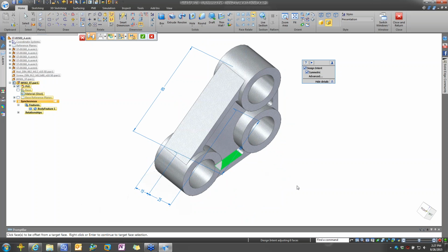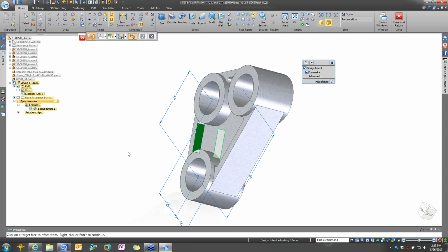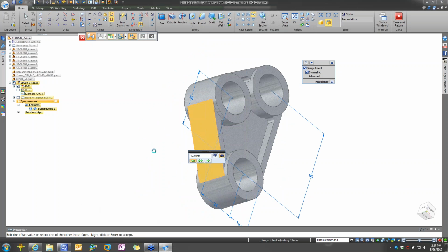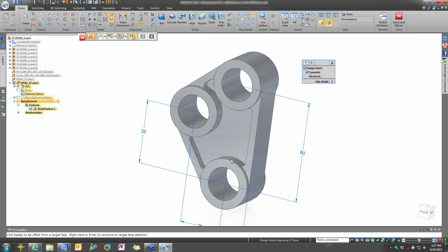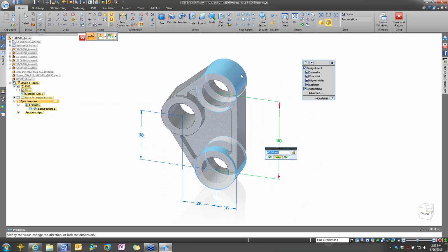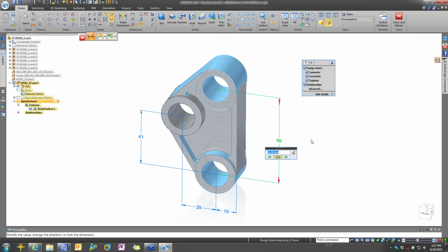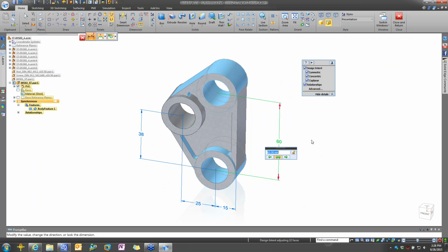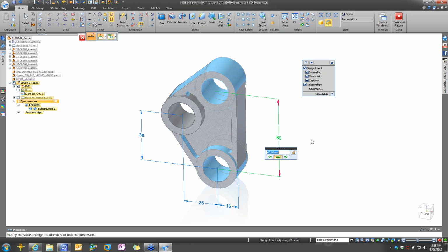And we'll do the same thing down here. So again, I don't have to go into any 2D sketches. I don't have to redraw or rebuild any 2D sketches. I'm working directly with the solid model. So again, let's make that change now to the dimension. And you'll notice that Solid Edge is going to maintain the symmetry because the part as it was brought in was symmetric. But what if my design team wants to make some changes to where now we don't want a symmetric part?